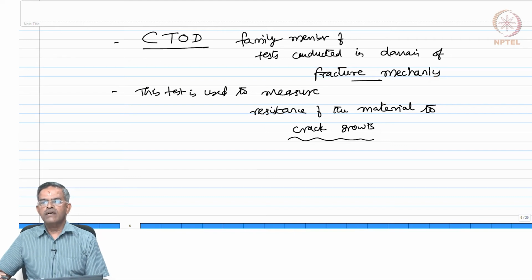So, you can very well see here we are imposing certain serviceability conditions not in the design scheme, but in the material scheme itself. Like the material should be non-corrosive, the material should sustain cyclic loads, the material should oppose a crack growth, and the material should be weldable and ductile, which were earlier considered to be design properties recommended in the structural design.